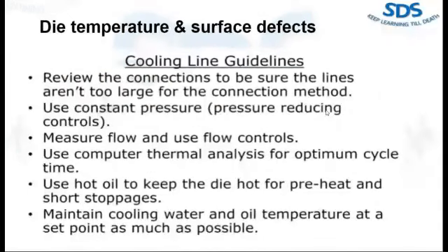It is important to review the physical connection of the cooling line to be sure the lines are not too large for the connection method. Many times the connection is the restriction in the line that controls the available flow rate. Use constant pressure control, and measure the flow and use flow control.